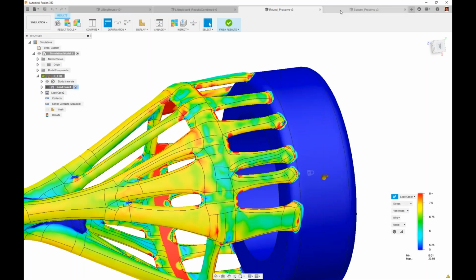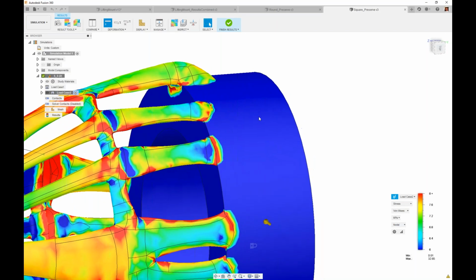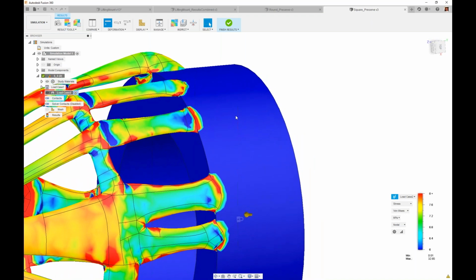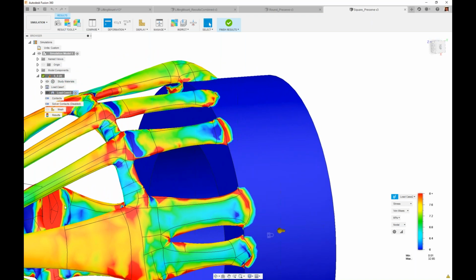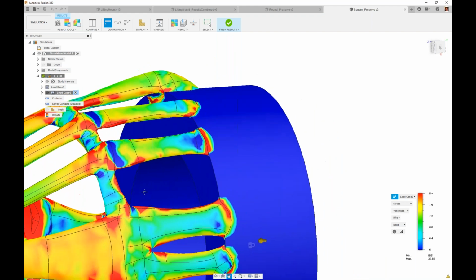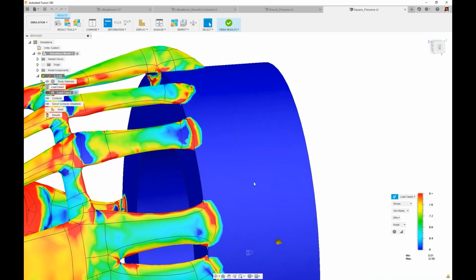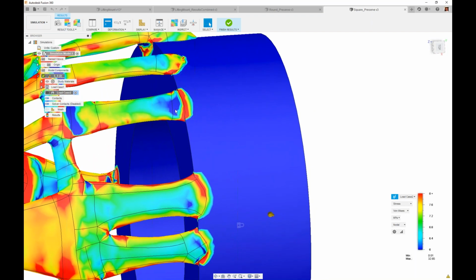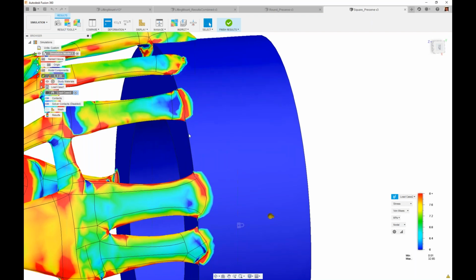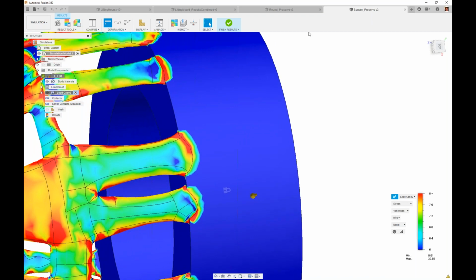So if we take a peek, I'll start with the square one, looking at some of the stress concentrations, which by all means is not for this geometry the highest stress concentration, but for this region of interest, bracketing the legend, most of the attachment points are fairly high, 7+ megapascals for how these legs attach into that preserve region.